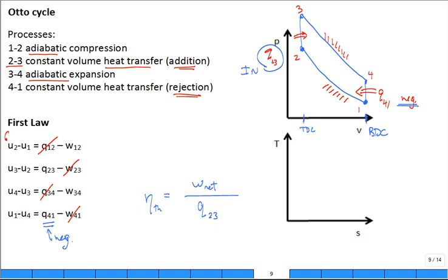Right. Okay. So, what does the temperature entropy diagram look like? What about the process from 1 to 2? What's it look like? Well, it won't be a square, but how about 1 to 2? Like that? Is that 1 to 2? Why is it constant S, 1 to 2? All processes are reversible, so no entropy generation, and no Q, so I'm not bringing in or taking out any entropy with the heat transfer, and I'm not generating. So you could write the second law. I didn't really do it, did I? But you find S2 is equal to S1.